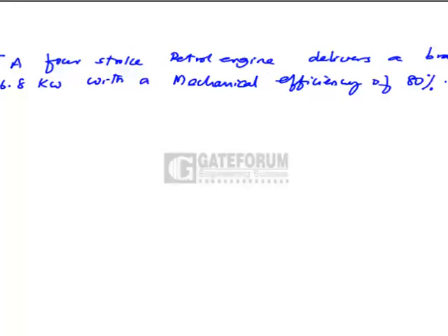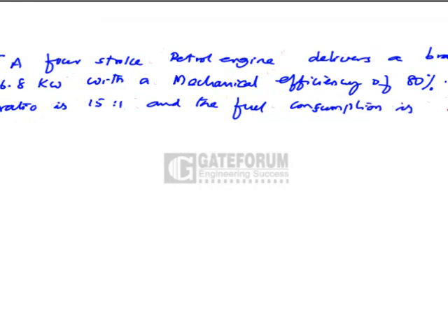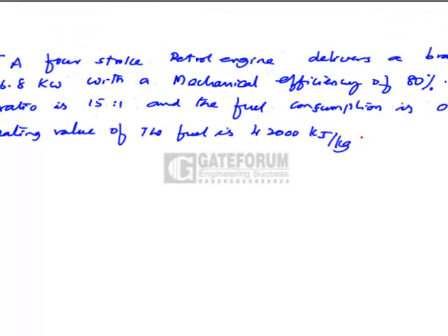The air-fuel ratio is 15:1 and the fuel consumption is 0.4068 kg per kilowatt hour. The heating value, which is also known as the calorific value of the fuel, is 42,000 kilojoule per kg.